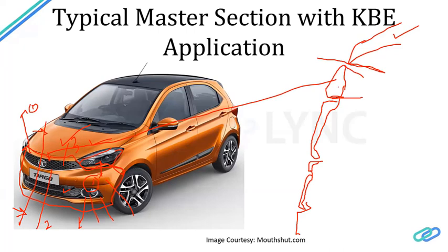Again, this is created based on the master sections, like what should be the clearance between these parts. As an input for this part, I will have this as a first flange, and then I will create this part based on the tooling recommendation: what is the tooling direction, where the parting line is coming.